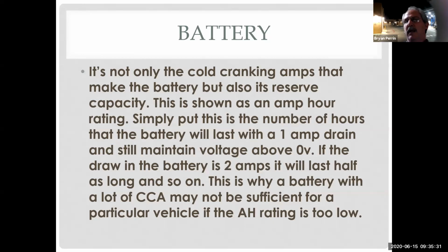And we see this a lot when people put lower amp hour, cheaper batteries, but they have the CCA, into a luxury vehicle. Right? Why do I need to buy that expensive battery? This one will fit. See, it starts the car. I knew I was right, but gee, if you let the car sit for 4 days, it's dead. So then what? They think they need an alternator. So they're going to go back to the same XYZ auto parts and buy an alternator because they got the wrong battery. And guess what? That's not going to fix the problem. So then they think they have a drain on the car they're not supposed to have. So they're looking for that, all because they cheaped out and put the wrong battery in.